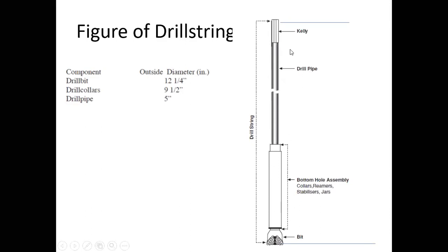The second thing is that the above portion we try to keep suspended. The above portion provides the tension in the drill string, just hanging tension in this pipe. But the lower portion provides the compressive force to the bit. So it tries to compress the bit.